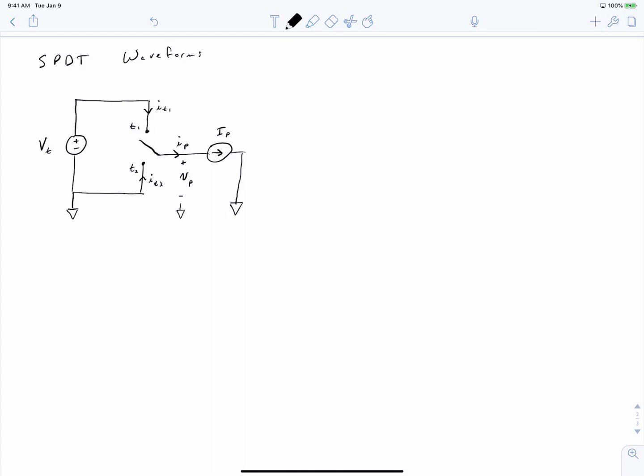So this is an equivalent circuit model. So similarly to how we modeled a linear regulator as a voltage divider, we're modeling a set of semiconductors that we haven't talked about yet as a mechanical switch that can connect a pole to 2 different throws. And so carrying this over to our linear regulator analogy, we have our unregulated voltage on the left side, and we are going to connect this pole to the different throws to achieve a regulated output voltage VDC on the right side. So let's now talk about the operation of this and what the waveforms look like.